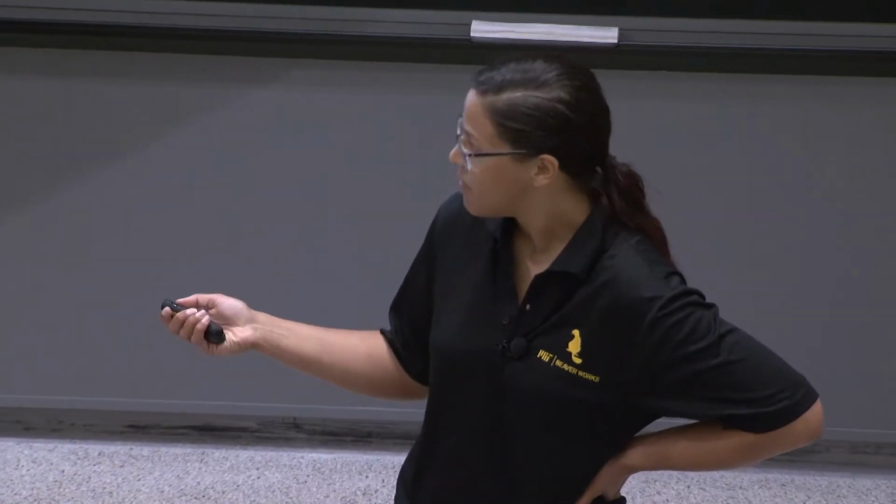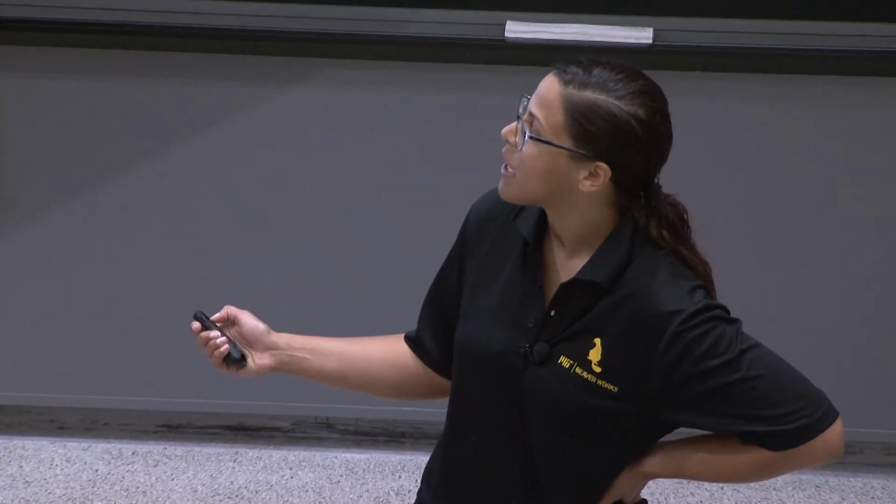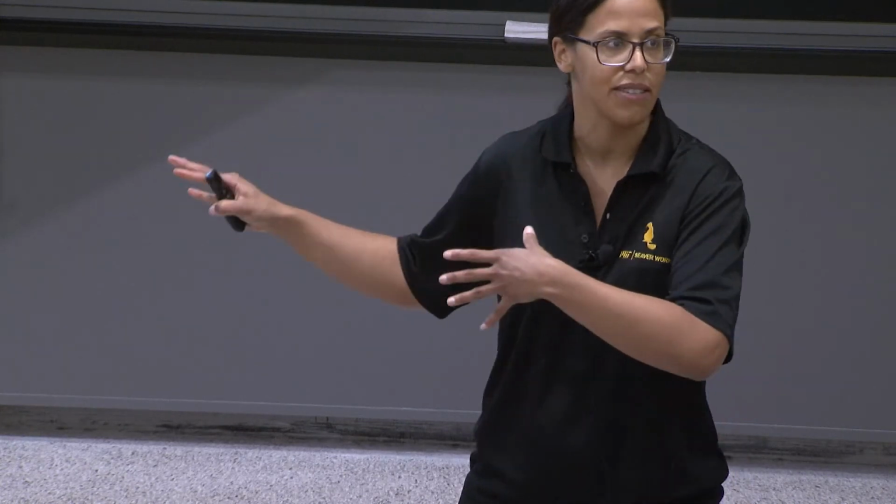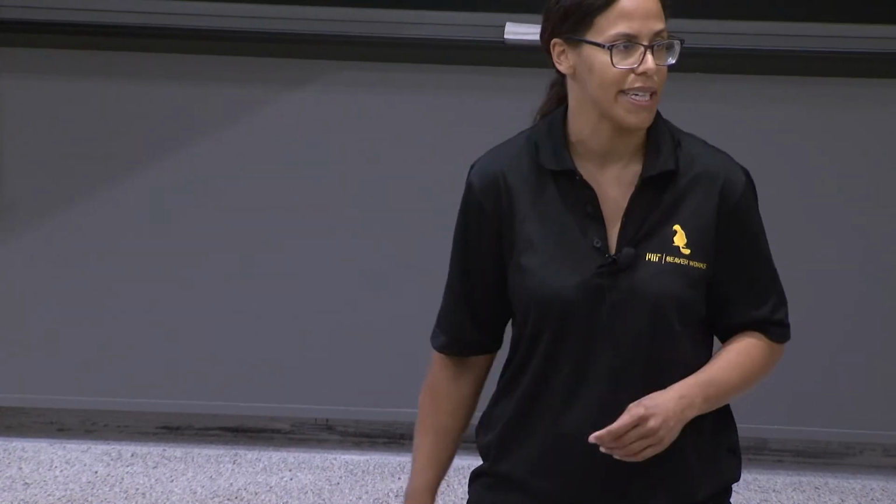Last time I presented this, I jumped straight to the error signal, but I wanted to show you why I defined the error signal this way. And later on, when you guys are in a team, you're going to go through the steps of defining the coordinate frame, defining what your reference input is, defining the error signal. So I want you to know the steps of what's going on. And that's more important, I would say, than the actual specifics for this particular application.